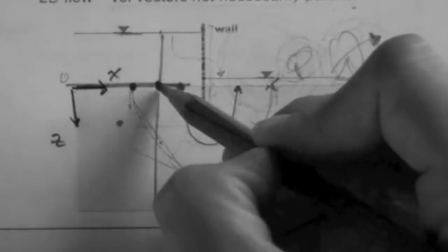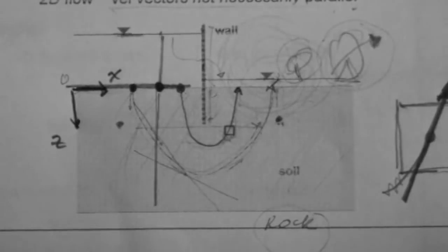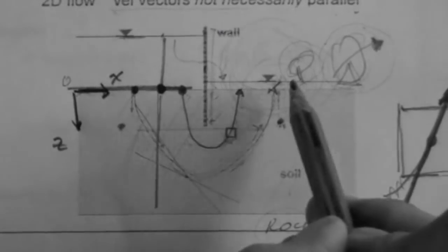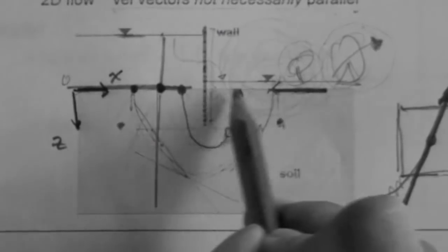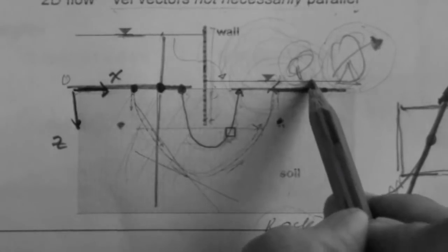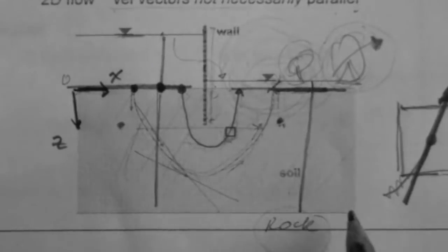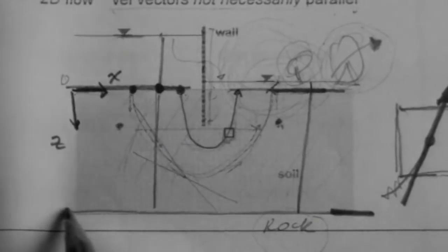So we know the total head at any point along this boundary. That is a boundary condition. So we can use that boundary condition to solve the equation. What about on this side? Yes, along this boundary, the pressure head is this little distance here, and the elevation head is that distance. Of course, we have assumed that the datum is this.